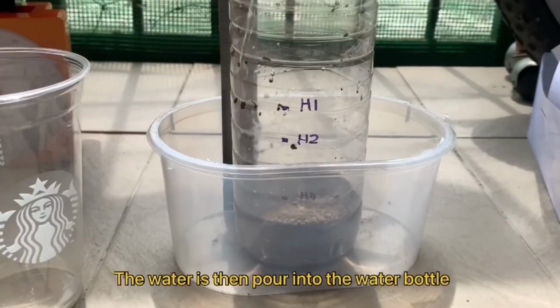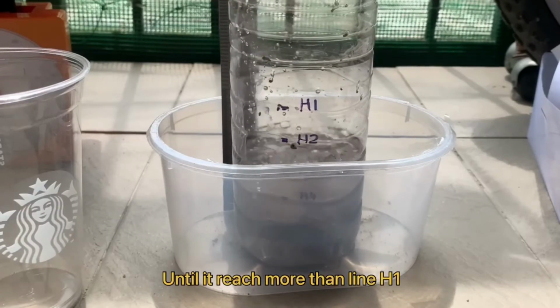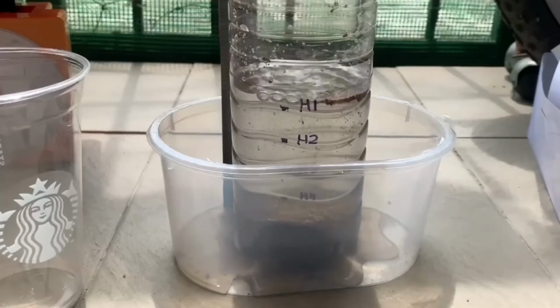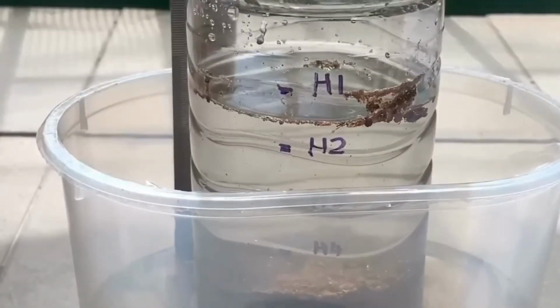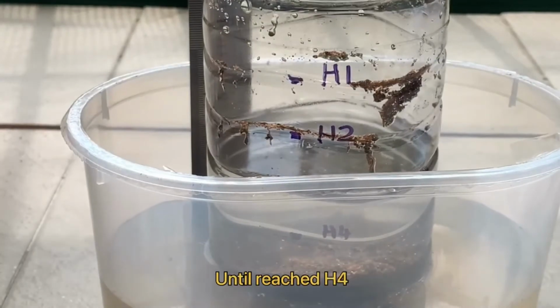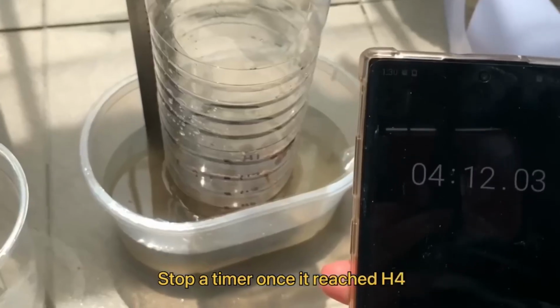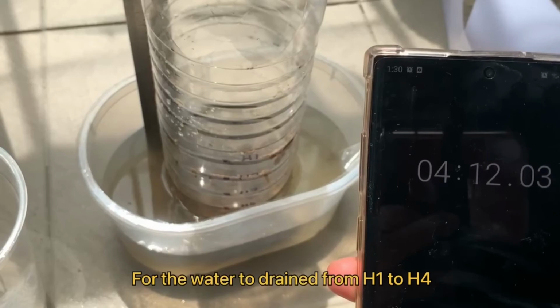The water is then poured into the water bottle until it reaches more than line H1. Set a timer once the level of water reaches H1. It may take a while for the water to drain out from the water bottle until it reaches H4. Stop the timer once it reaches H4. As you can see, this is how long it takes for the water to drain from H1 to H4.